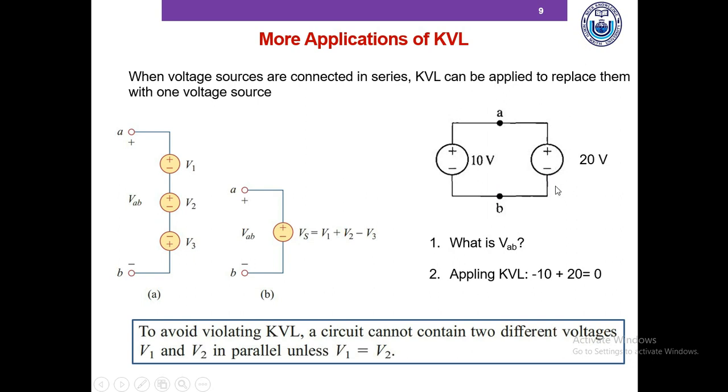You can see this is an invalid connection, because you can only connect multiple voltage sources in parallel if they have the exact same values, but they don't have the exact same values, which is why this connection is invalid.